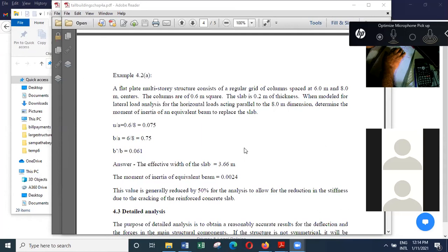One of the problems that occur in tall buildings is that they are almost like cantilevers fixed at the ground level. So when you have a cantilever, it will deform when it is subjected to lateral loads. All tall buildings will behave with certain deformations, and on a day with heavy wind, you will find that the building can move as well.